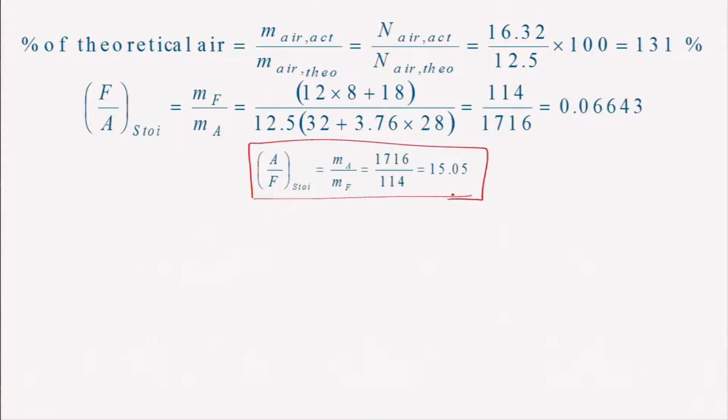This is your case. This is basically a hydrocarbon, and so also methane is a hydrocarbon, but in the case of methane we have seen the air fuel ratio is around 17.16, but in this case it is 15. You keep in mind that for unsaturated hydrocarbon, except methane, most of the air fuel ratios will be roughly 15. You can keep in mind that ballpark number, the air fuel ratio required for complete combustion.